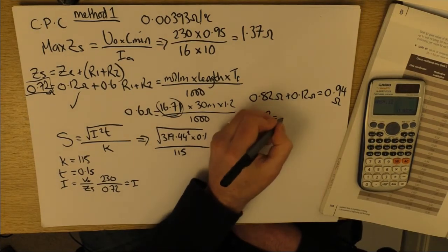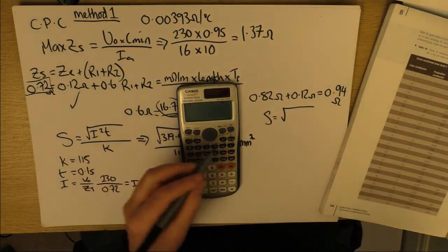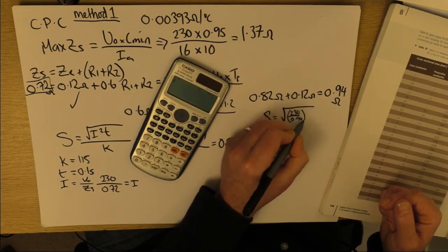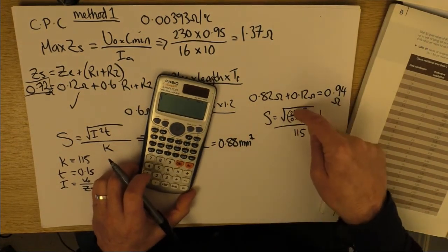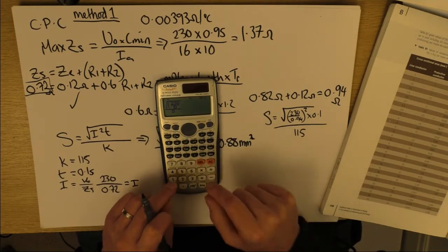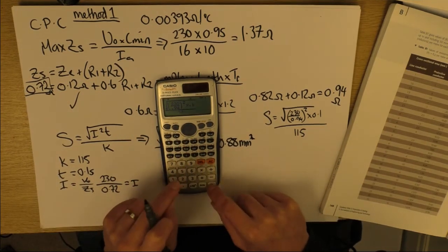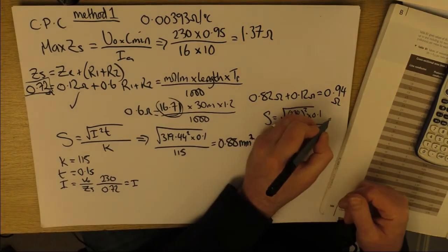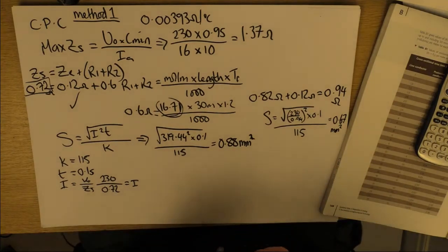And then just check the adiabatic with that. So I need a new fault current. I could be fancy pants and put it in like that, couldn't I? So I've just replaced the I with the equation to get I. Don't have to do that, obviously. Squared times 0.1 over 115. 0.67, so we could have used 1 mil, but as I say, sometimes you want a bit of mechanical strength, and that might be a consideration as well.